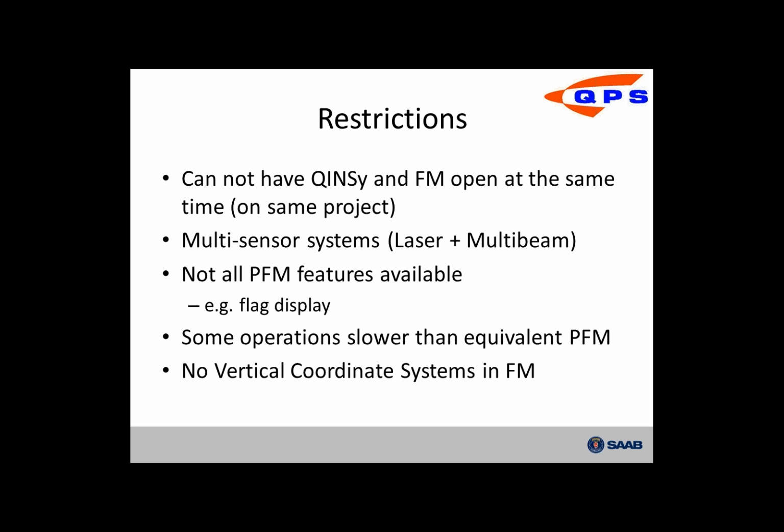Also, as I mentioned, there's no vertical coordinate system support in Fledermaus, so you have to ensure that you're not mixing your vertical coordinate systems in Fledermaus.